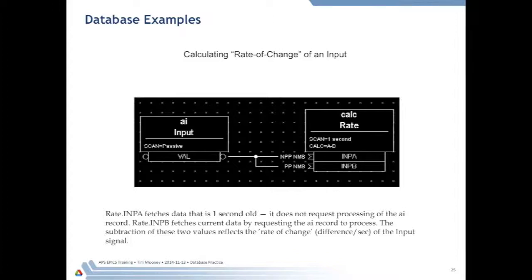And then the next time you process it, you'll probably find that value. And that's one of the reasons why people say that EPICS is best driven from behind. It's better to put stuff than it is to grab stuff, right? Because of this, because you don't really want to be thinking about whether or not this is an asynchronous record. You might not know. You might not be able to tell. So anyway, that's basically how links work and the difference between NPP and PP.